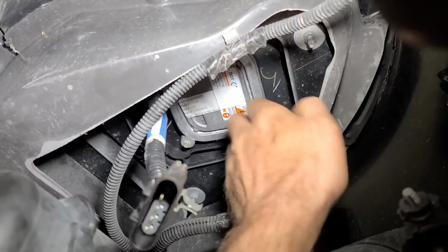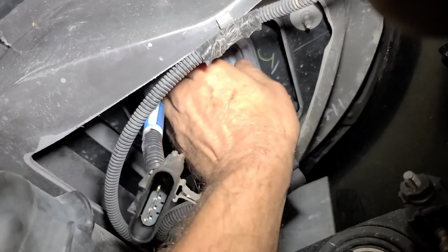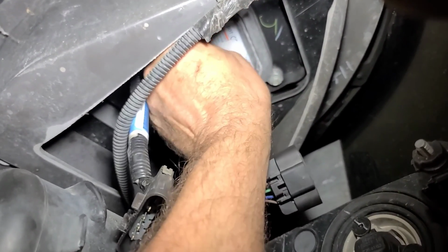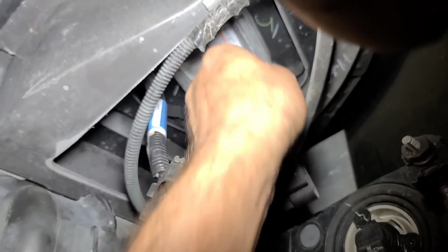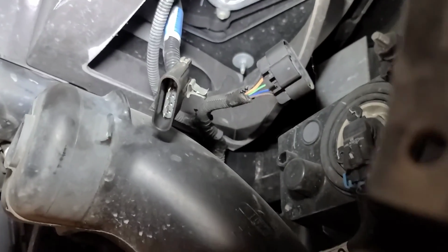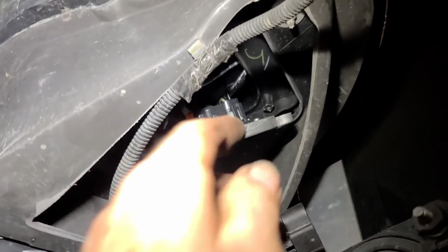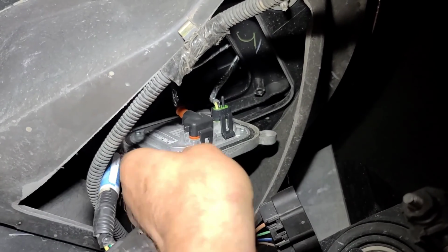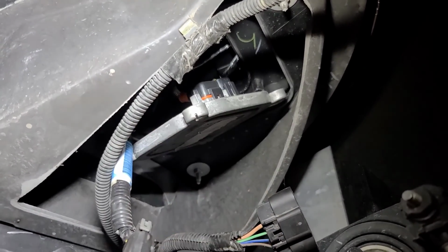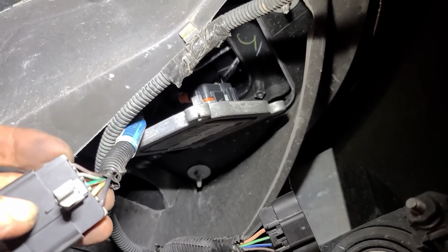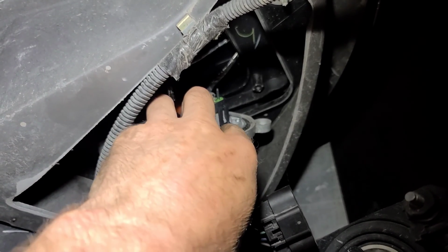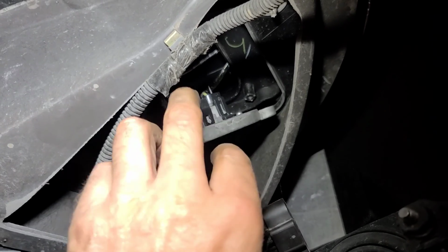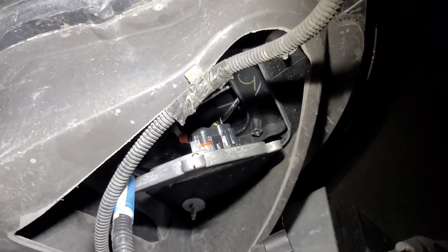Then I also see what appears to be a ballast on the bottom of this headlight. So I'm wondering if I take that out and see if there's any connection. It doesn't show it in the schematic though. So I guarantee you that's the ballast right there. And there's the black and yellow wire coming from this connector. So we're going to check for power here at this black and yellow wire, and if we have power, then we need a ballast. Why doesn't it show that in the schematic as a separate component?